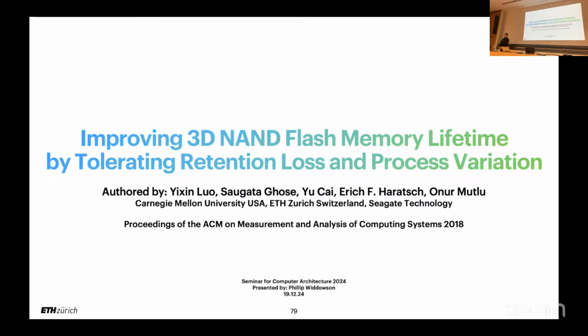This is actually implemented in flash controllers today. A lot of things that you covered in earlier papers, like neighbor-assisted correction, are implemented in existing SSD controllers today. They do a lot of other processing, like LDPC decoding and soft decoding. This is a very fascinating area where very little is actually exposed to the real world other than some of these papers.